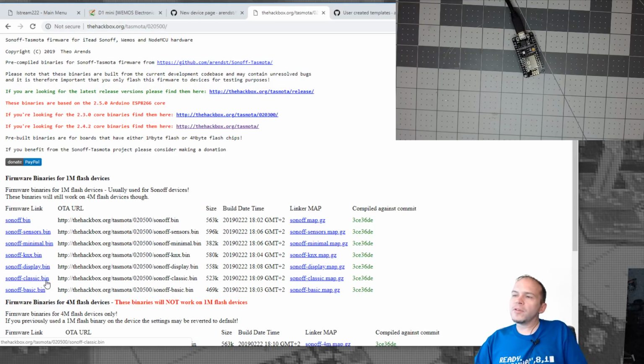Yeah, I did put a different bin file on that little fork for that Martin Jerry dimmer. And really the only major difference in there was, because of the Tuya Convert stuff, I made Wi-Fi Manager the default. So if you switch over to one of the dimmers, which I've got four dimmers here I've got to do for a project later after this live stream, if you're doing the Tuya Convert and you mess up on that password, or you have special characters in that password that don't jive with Tasmota or even the Arduino core, you'll end up getting that device stuck where it won't hook up to Wi-Fi, and it'll just continue to try.